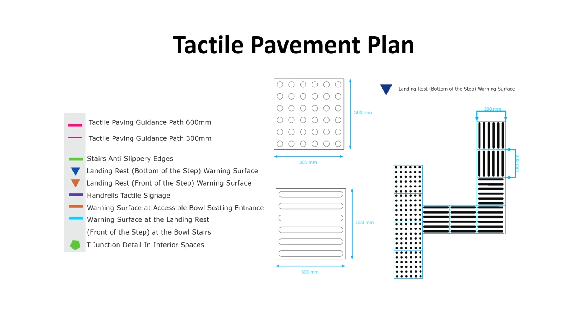During the implementation phase, the construction team follows the layout plans to install tactile pavings according to the design specifications. This includes carefully placing the tactile elements in the designated area, ensuring that they are aligned correctly and securely fixed in the ground.